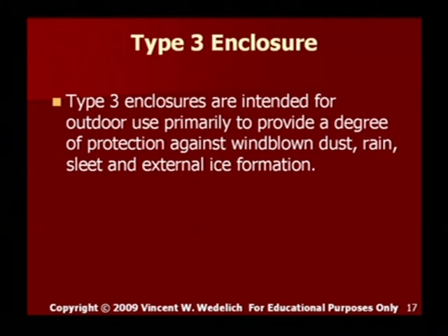I'm going to go ahead and talk a little bit about enclosures. These are NEMA type enclosures, because we do talk about different enclosures, and I'll compare these NEMA or American enclosures to IEC enclosures. Obviously the first one I'm not showing here, but it's a NEMA 1 or type 1 enclosure, and that's just a general purpose indoor enclosure.